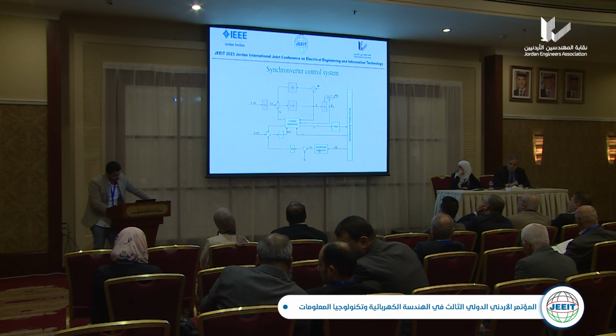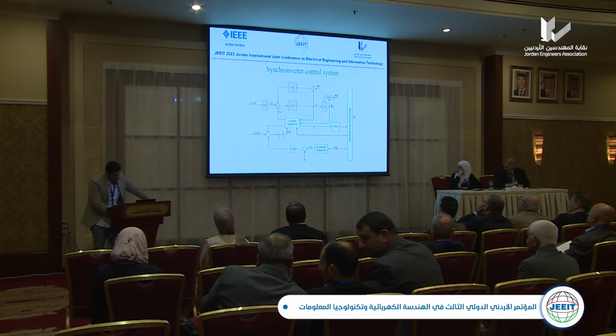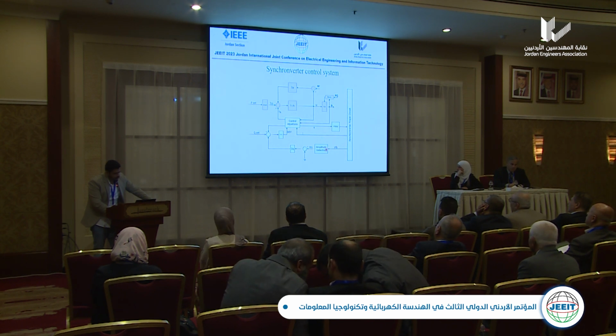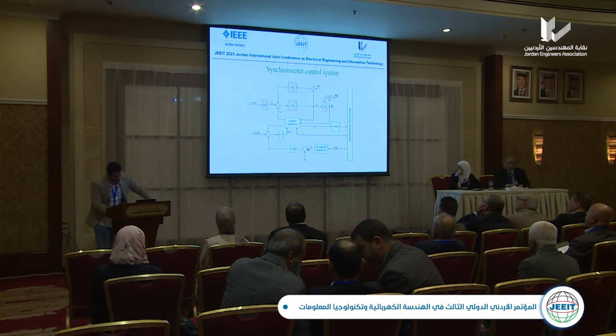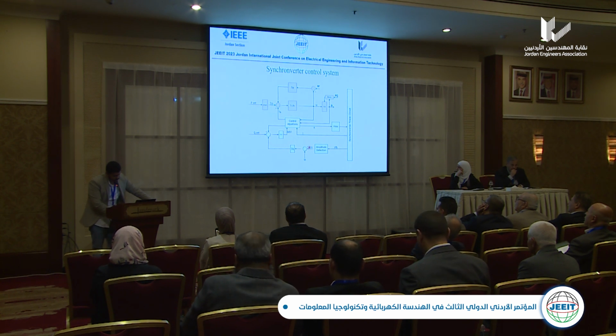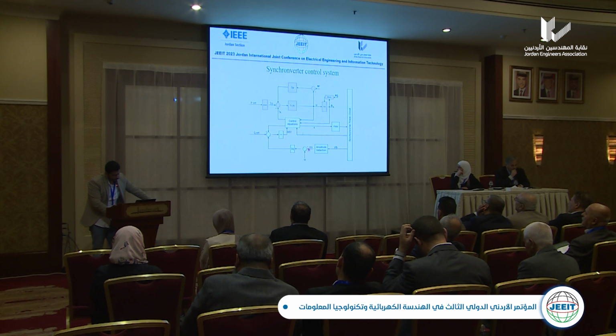To get the dQ, we go to the synchronverter power circuit and take a feedback voltage signal and enter it with the amplitude detection tool to give us Vm. We take the difference between the reference voltage and the amplitude that we obtained to give us dQ.